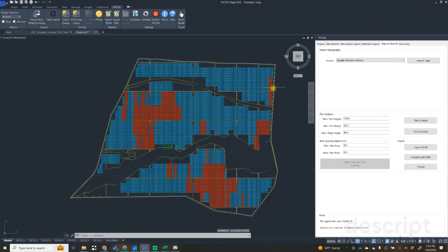And then finally, we have a PVCAD export. So if we click PVCAD here, what it will do is give us an export in a zip file. Unfortunately, PVCAD isn't a single file import, so that zip file contains a folder directory that replicates the locally installed PVCAD data directory. So what you have to do is just take the export file contents and get it into their corresponding files for PVCAD. And from there, you can go ahead and do your shading scene analysis.